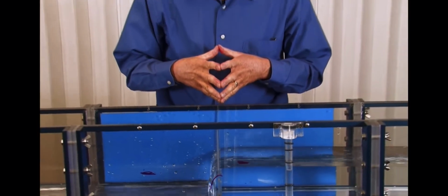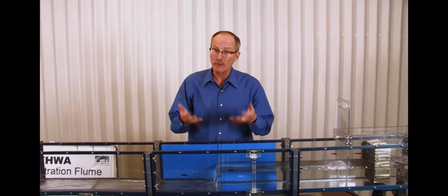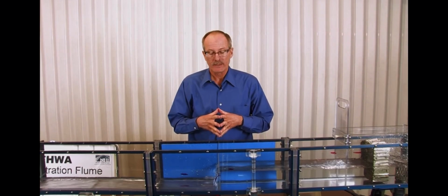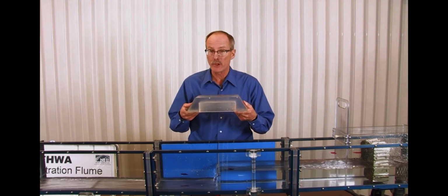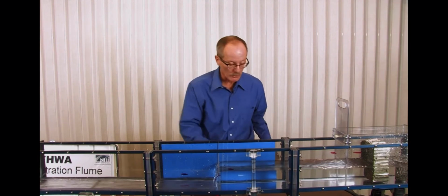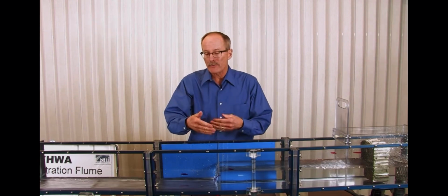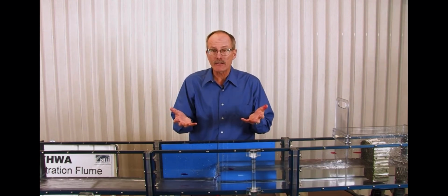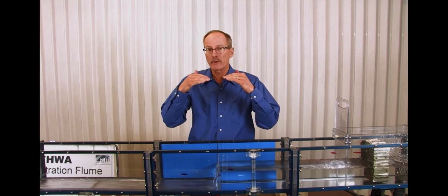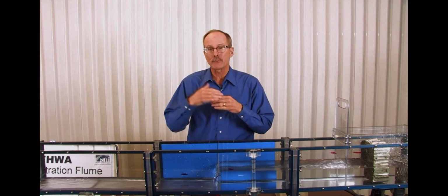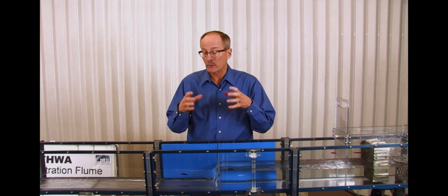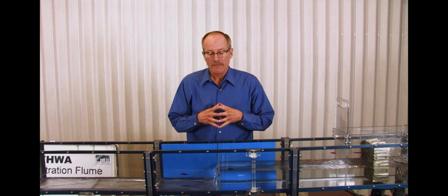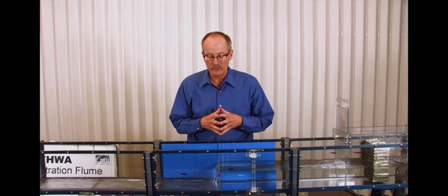So the weir equation is important in highway drainage design because it underlies many of the calculations we do. We might apply it directly when we're looking at overtopping conditions, say after a flood, how much water was going over the top of our roadway. But it's also part of a culvert analysis in inlet control, before the culvert starts to seal off, before we get ponding at the upstream side. It's kind of acting like a weir. It's part of our grate inlet designs. So it underlies many of the calculations we do.